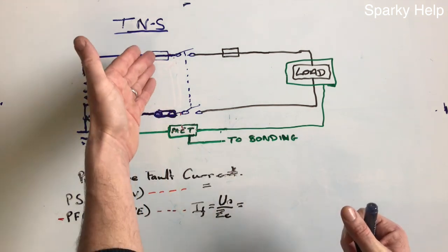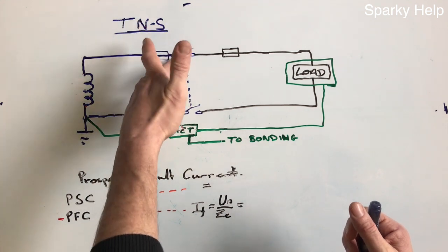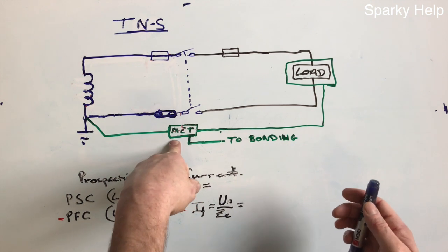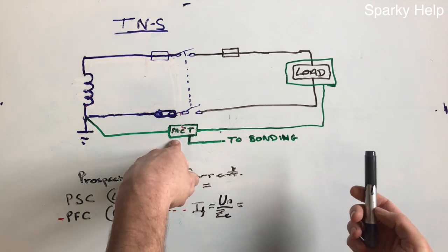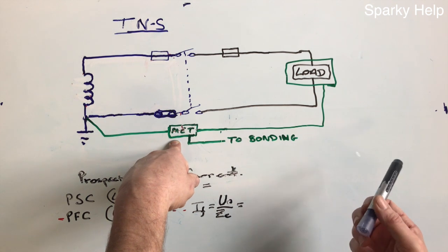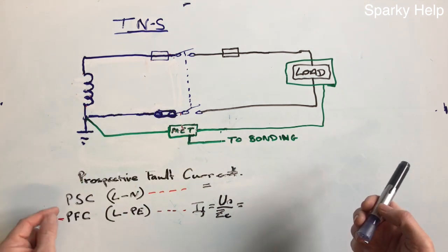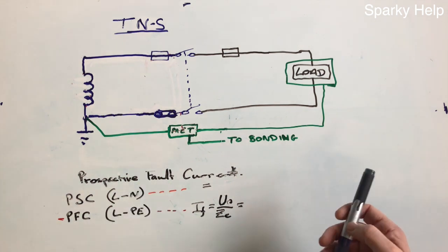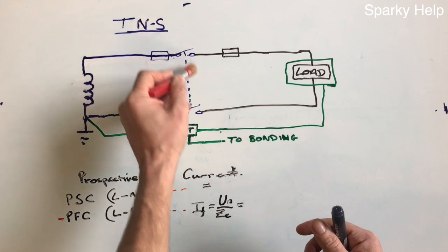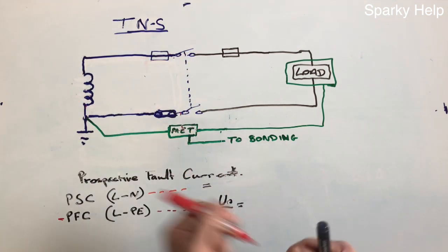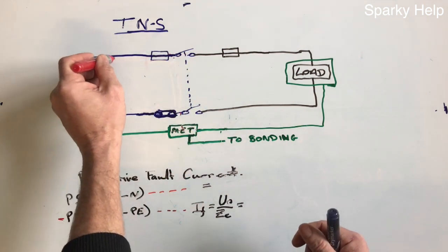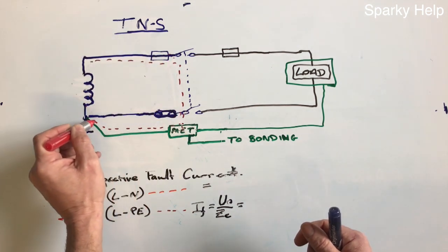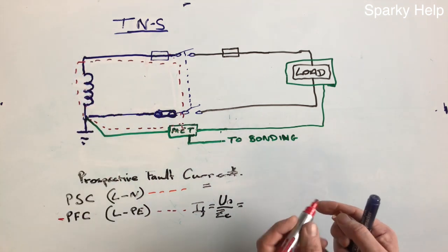Remember, locked in the off position, we put a line conductor on there, a neutral conductor on there, and an earth conductor on there from your earth fault loop impedance tester, and we set it to fault current. We want to set it to measure the LPE first, and the fault current will flow around in this location. So I'll just put it on again. Down there, and it flows now back through the sheath and around.